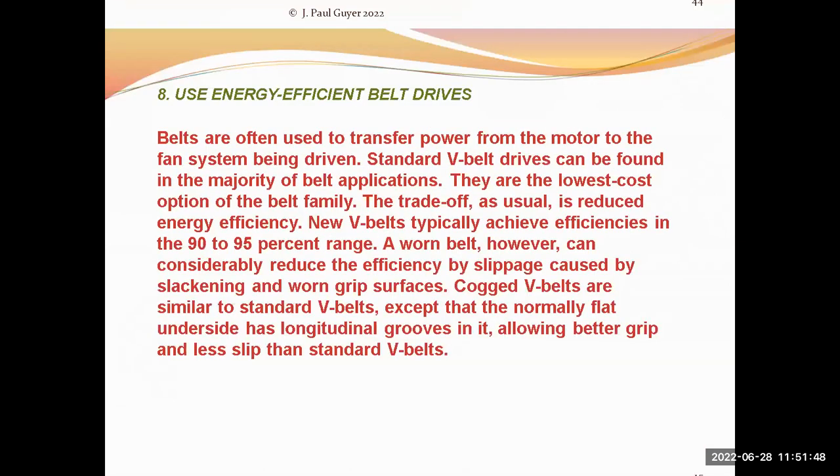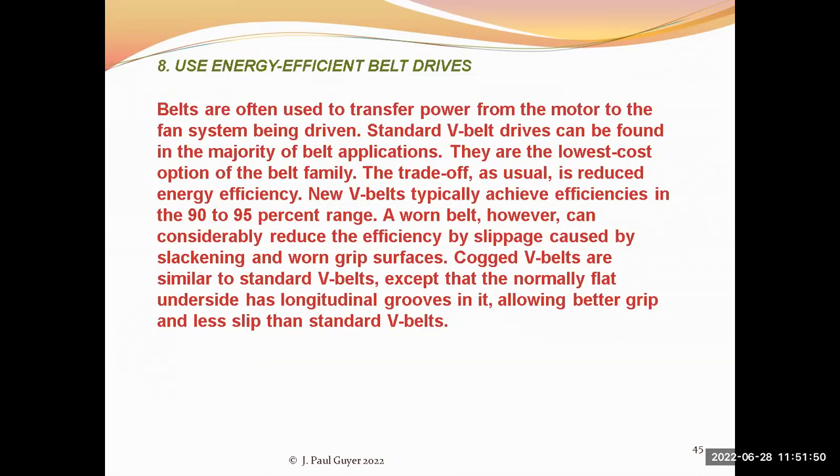Also, another product that is on the market is energy efficient belt drives. In your air handler, of course, you've got the fan that's being driven by the motor, and there's a belt drive connecting the motor and the fan. Standard V belt drives are found in the majority of applications because they're the lowest cost option.